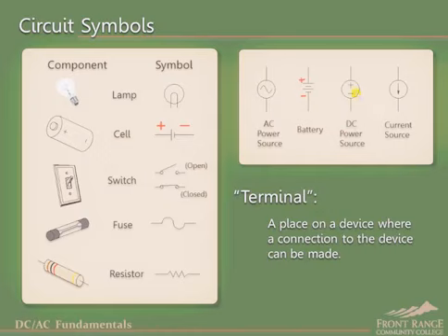It could be a battery, or it could be a DC source derived electronically from an AC power source, such as a portable AC power supply plugged into an outlet and used to provide power to a laptop computer or other electronic device. Last, on the far right, is the symbol for a DC current source. Physical devices that act as current sources are derived from voltage sources with some additional components. Later we will see that when analyzing circuit behavior, it is sometimes convenient to treat one or more energy sources as if they were current sources instead of voltage sources.